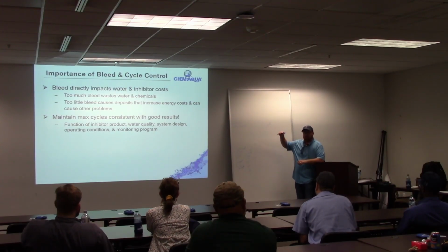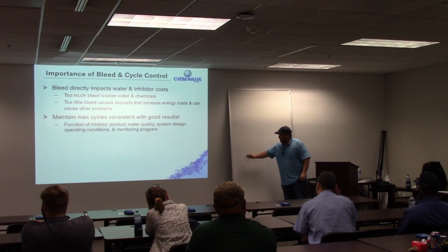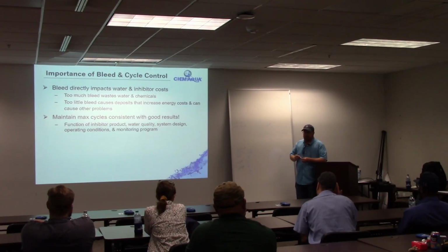You can only cycle that up to a certain point before it becomes oversaturated, and it's going to precipitate out and start causing problems. And so that's why blowdown set point, conductivity set points, and cycles are the heart of water treatment. That's why that's so important.